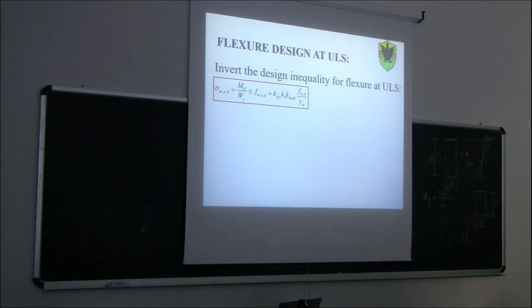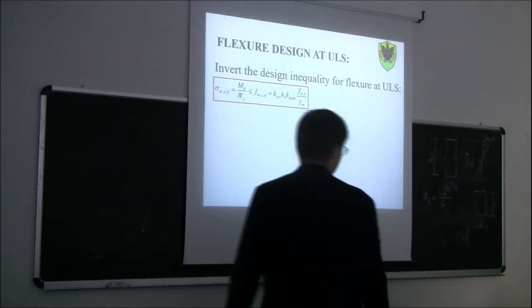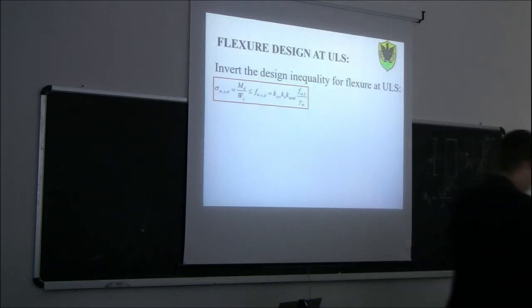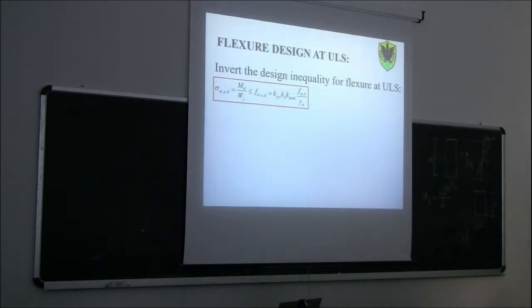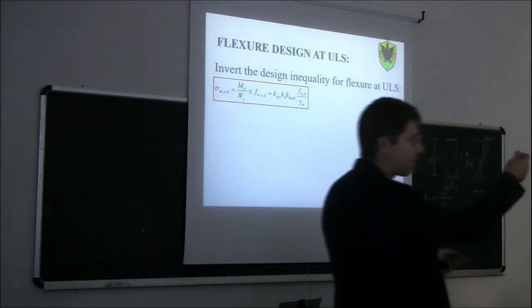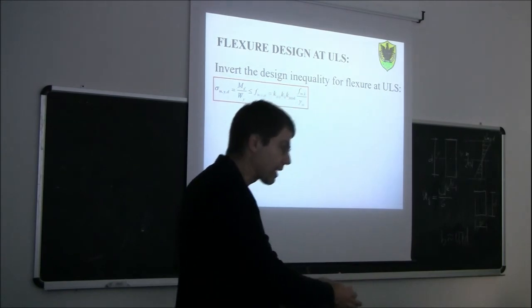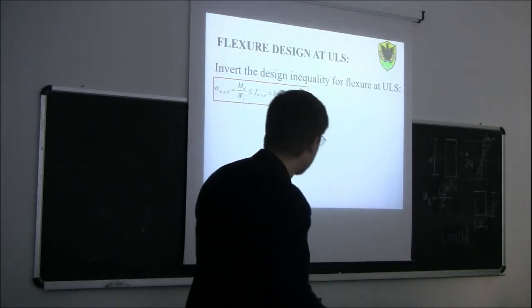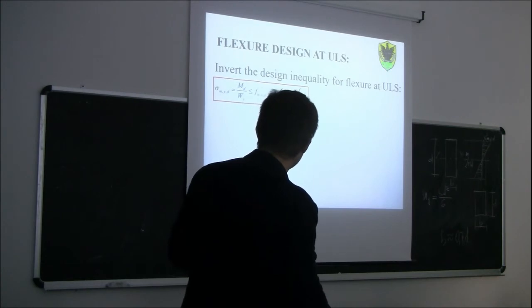For glulam, instead, this relationship is not valid anymore, because for glulam, if you remember, usually we have a very narrow cross-section, very high, like in our case. So for glulam, we need to make an assumption. For example, the breadth. We can decide in this case to keep the breadth at 18 centimeters and calculate. If you remember, in the preliminary design we said 18 times 1.5. We keep the 18 and we calculate the right depth in order to satisfy the equality.